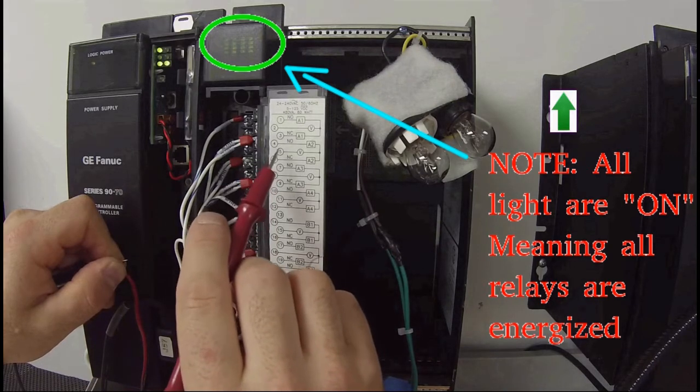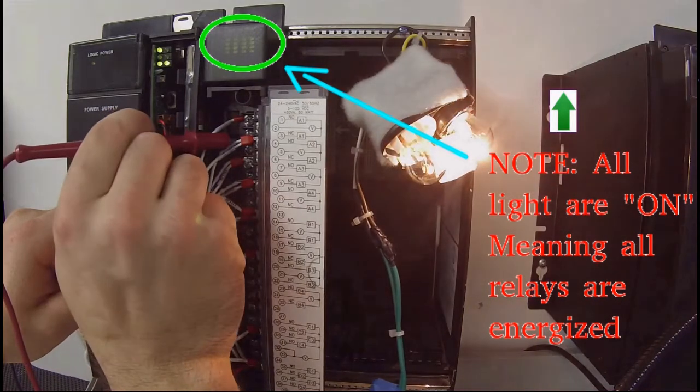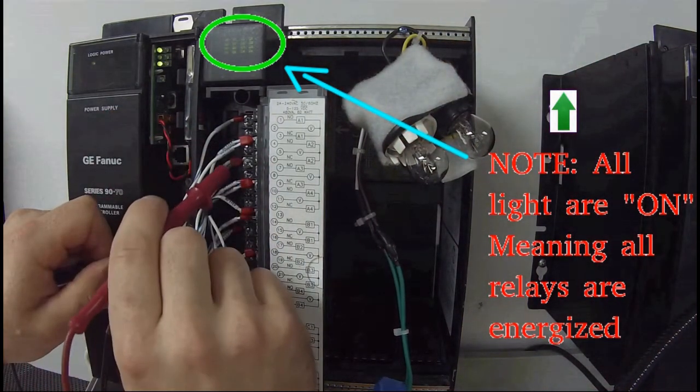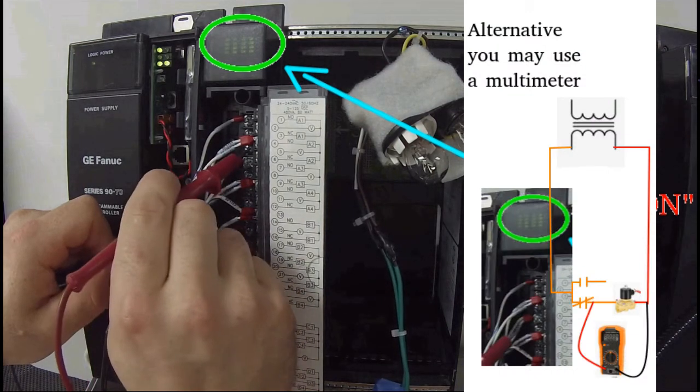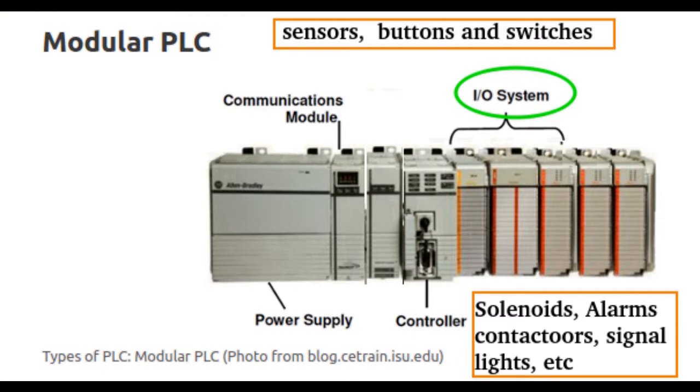Terminal number 4, normally open, is now closed. Number 6, normally closed, so that should be off. 7 should be on. Besides troubleshooting the inputs and the outputs, which is where you're going to find the most problems,